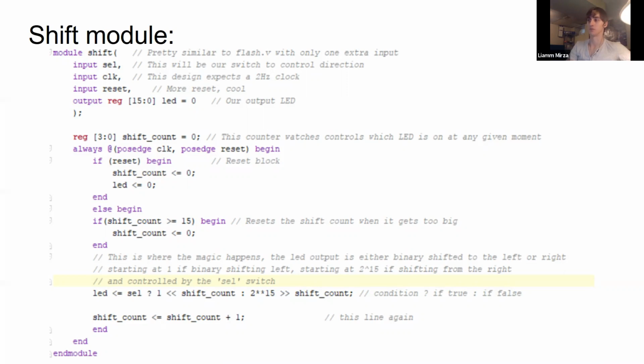You're always at a loop with a posedge clock and a posedge reset. You're going to be seeing that a lot because that's your most common type. That's known as an asynchronous reset. That was also a question I think I got in either the midterm or the final. Yeah, I think you definitely should have seen that question around.